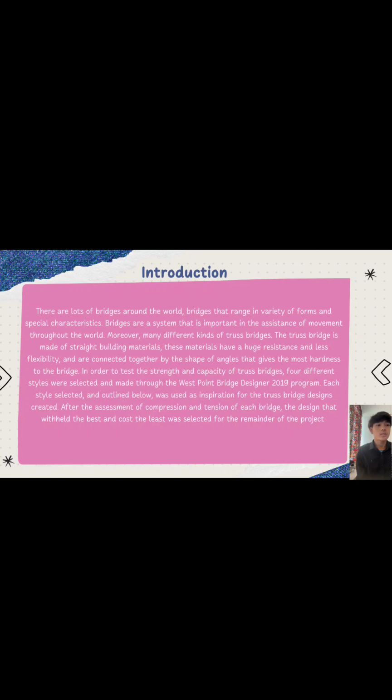In order to test the strength and capacity of truss bridges, 4 different styles were selected and made through the West Point Bridge Designer 2019 program. Each style selected and outlined below was used as an inspiration for the truss bridge design creator. After the assessment of compression and tension of each bridge, the design that held the best and cost the least was selected for the remainder of the project.